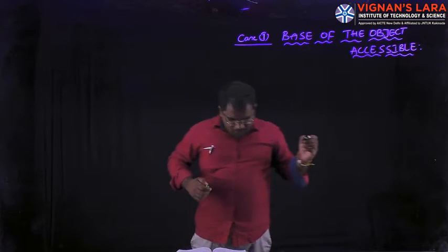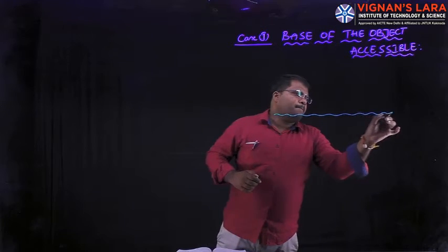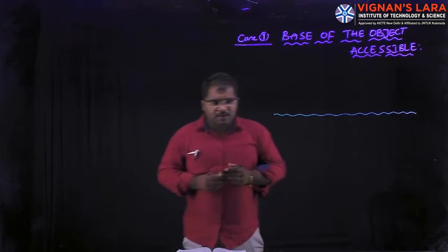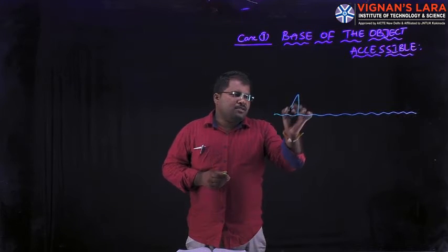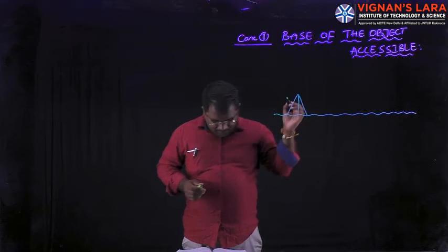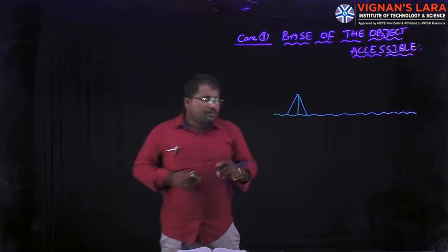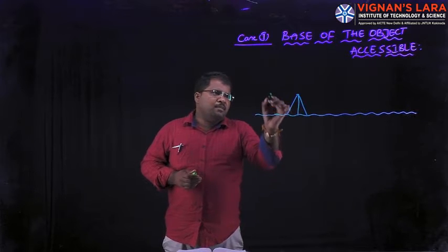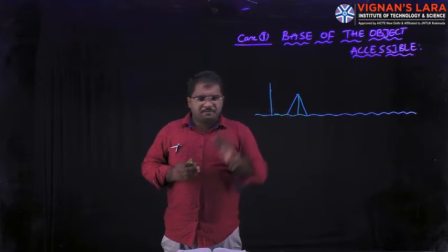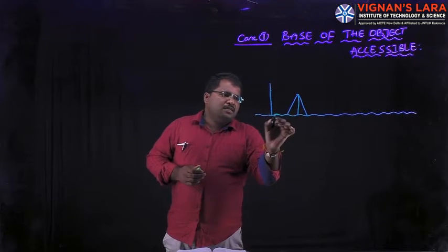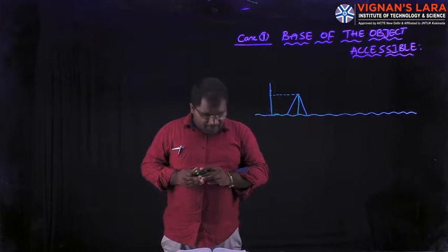Suppose I take a plane where I set up the instrument here, the theodolite. By keeping my leveling staff over a benchmark, I find out the height of instrument.